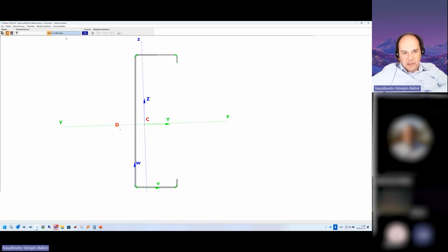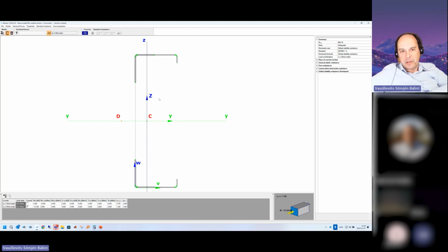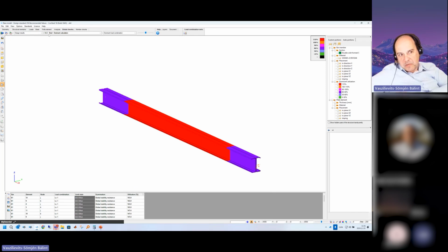And if I go to the other load case with the axial compression, we can see, as we expect, that the web is in compression. Therefore, there will also be an ineffective part of the web. Plus, similarly, but not only on the top, but also on the bottom flange, we have thickness reduction due to distortional buckling. But the section doesn't work, at least for the bending condition, we have more than 100%. For the pure compression, we are below 100%.